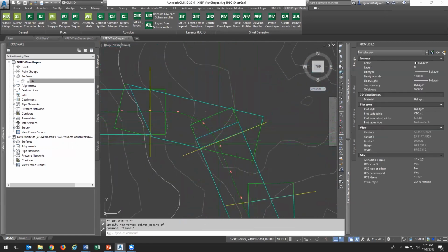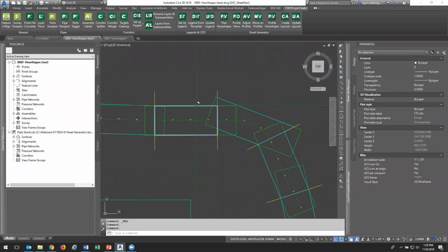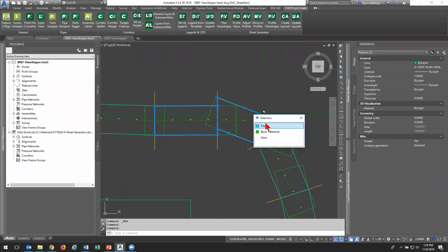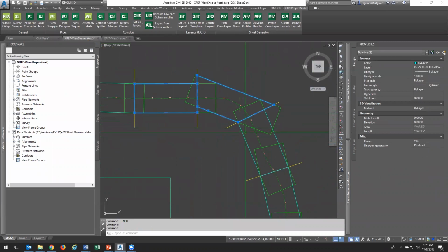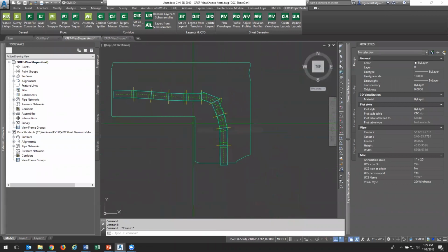Add vertices, move vertices, rotate, align, use your reference points. We're going to skip forward to this all being done and put together. And notice that I don't have any of my view shapes, these polylines, overlapping past the match line. That's our real goal, to make sure that one sheet is inside its master boundary and also trimmed by our match lines. And once we've got that all set up, we are done with this file.